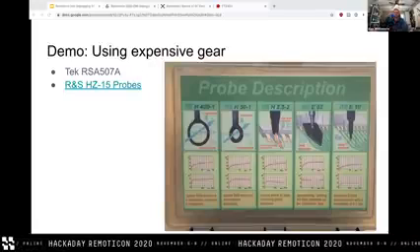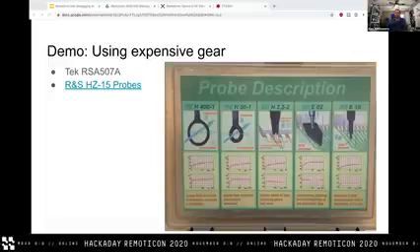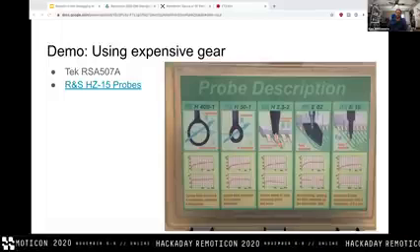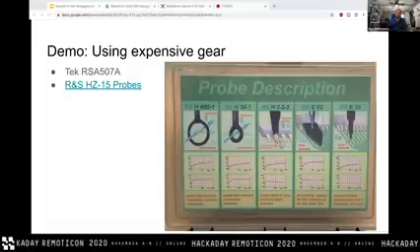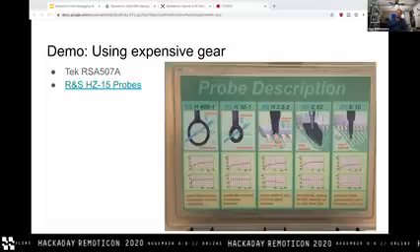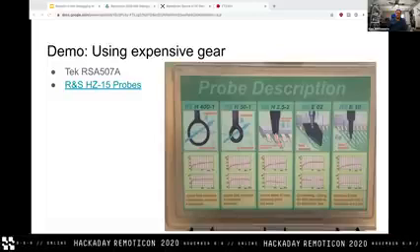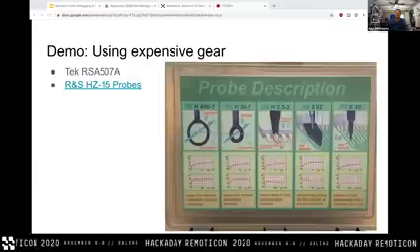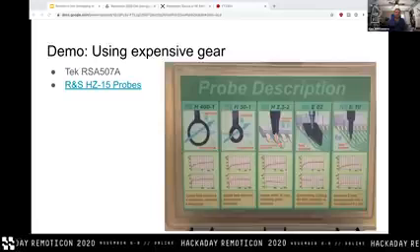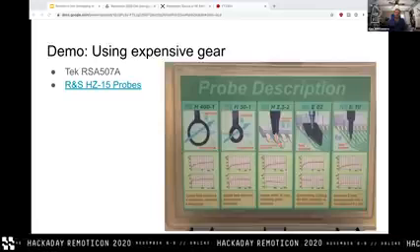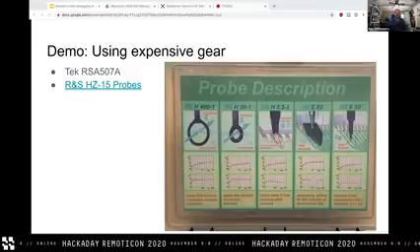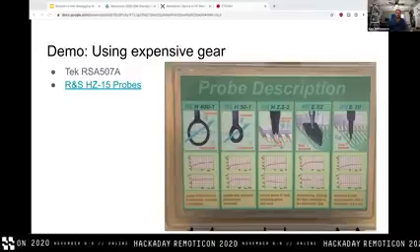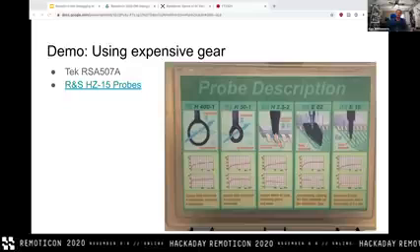The two types of near-field probe that exist are H-field and E-field probes, one of which senses the electric field in a volume of space, and one of which senses the magnetic field in a volume of space. So this is exactly the same way that a voltmeter senses voltage and a current clamp senses current by virtue of magnetic field. We've literally got a current clamp that uses air as the core for all of these H-field probes, and we've got, I don't want to say electrostatic, but basically a voltmeter operating in air, which is a little tiny antenna on the end of each of these E-field probes.